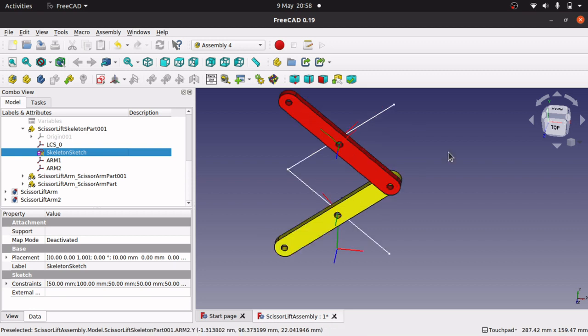What actually happens is that FreeCAD will optimize a model depending on the different faces that are in there. So this can happen with faces and pads, lines, edges, etc. So if you have pad 1 with pad 2 and then a pad 4, FreeCAD may end up optimizing pad 4 to become pad 3 and rename it. But if you've got parts relating to pad 4, then they may break. So you get this problem of renaming. That's exactly what's happening here.